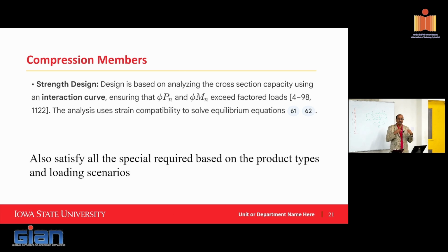An erector may say, hey, I'm going to do the construction this way, which is not outside of what you thought about. You need to make sure that you think through: will it introduce additional load? Will it introduce eccentric load? Will it introduce torsional loads? Those are things you have to pay attention to.